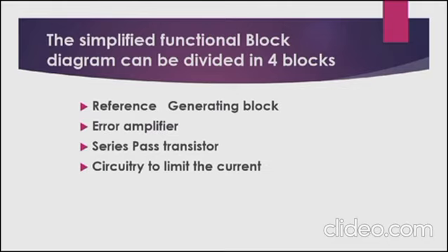The constant current source makes the Zener diode operate at a fixed point, and the reference is applied to the non-inverting terminal of the error amplifier. The unregulated input voltage plus or minus VCC is applied to the voltage reference amplifier as well as the error amplifier.